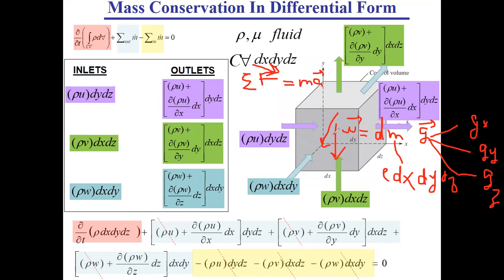Now, another type of force, as we said, is the pressure forces. So let's say I need to determine the pressure field. If I know the pressure at this face is Px, then at the second face here, it's the pressure at x plus dx. And I can use Taylor expansion to relate these pressures. So I can write that the pressure at x plus dx is equal to the pressure at x plus del p by del x dx.